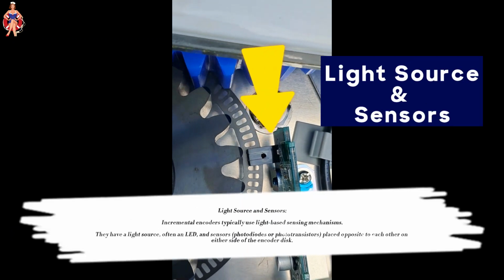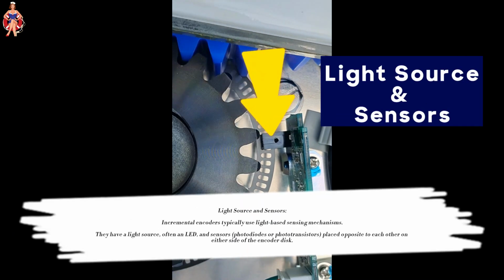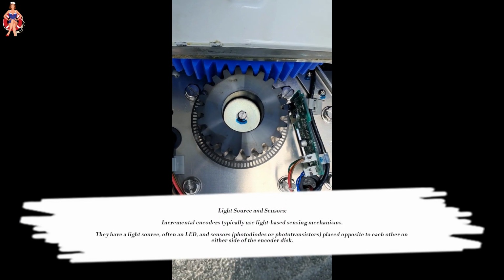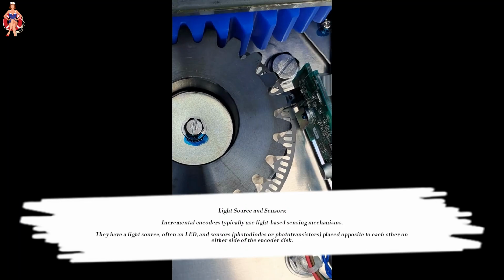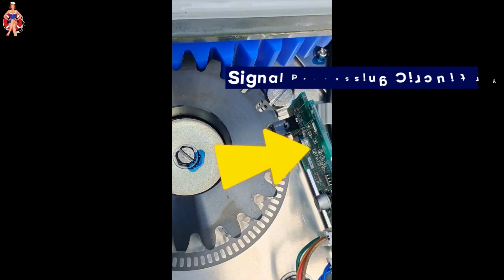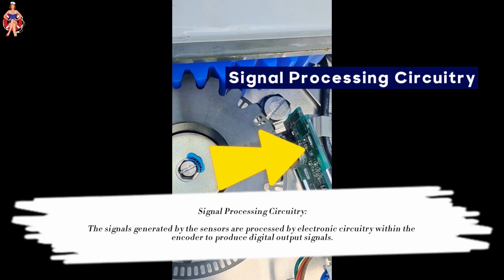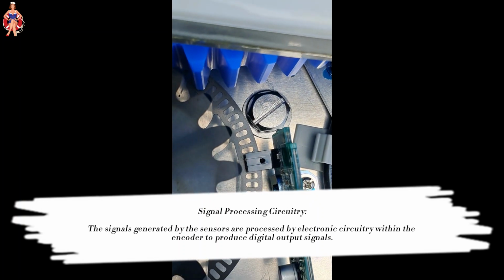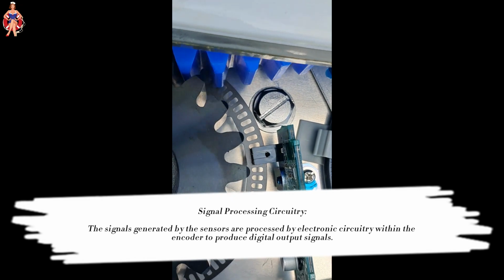Light source and sensors. Incremental encoders typically use light-based sensing mechanisms. They have a light source, often an LED, and sensors placed opposite to each other on either side of the encoder disk. Signal processing circuitry. The signals generated by the sensors are processed by electronic circuitry within the encoder to produce digital output signals.